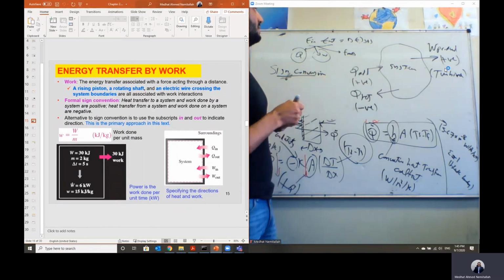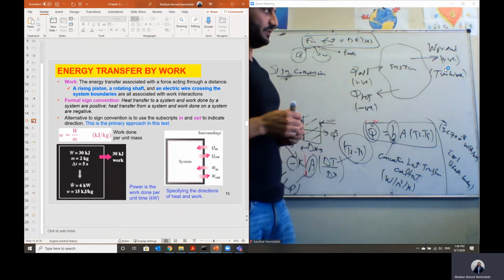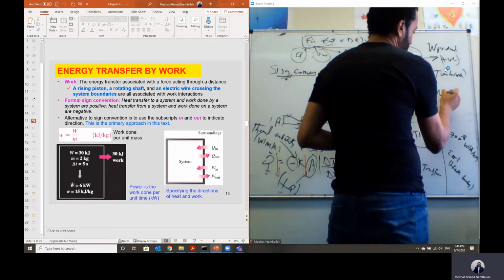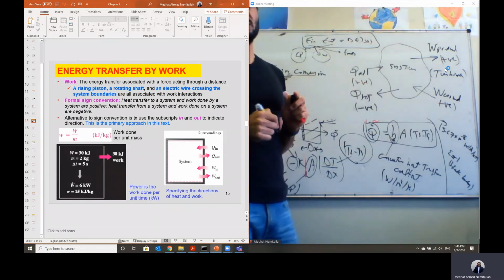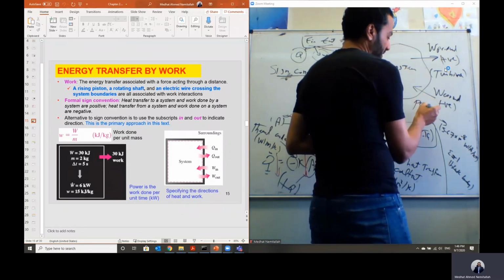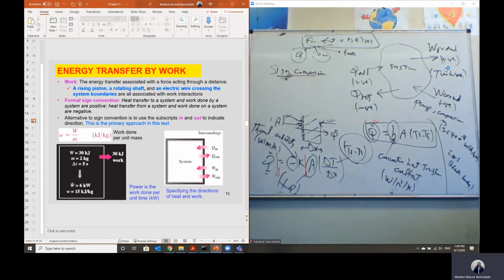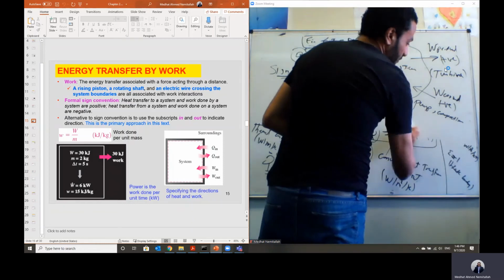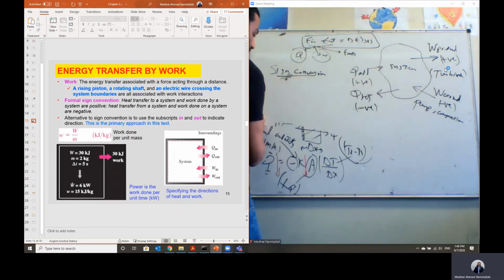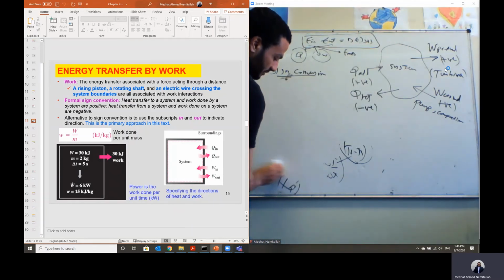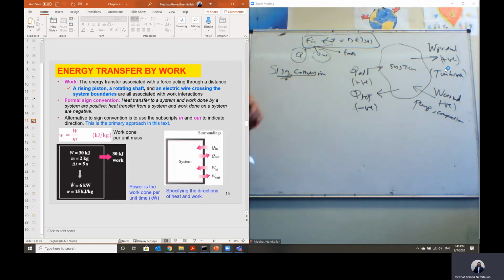If we have a turbine and we apply the first law of thermodynamics, the sign of the work of this turbine should be a positive value. But if we have a pump or compressor, this work is consumed, and we have to substitute it in the first law equation with a negative sign. Compressor and pump are the opposite of the turbine. In a turbine, we convert the flow energy in terms of high pressure into mechanical shaft power, but in a compressor or pump, we do the reverse. We convert the mechanical shaft power input to the pump or compressor into flow energy in terms of higher pressure.